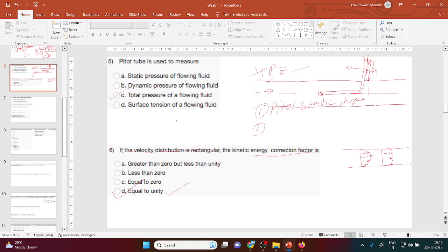Only on that do you get this height. With this height you measure the pressure inside the pipe. So this is the total pressure, not only from the velocity or only from the pressure. This height comes from the combination of both. So the flow becomes stagnant, and the whole energy of that flowing fluid is converted into that fluid inside the pipe. Is it like that?